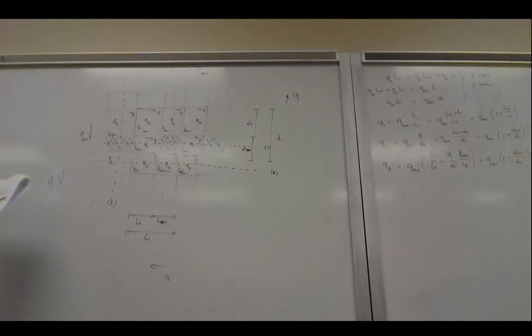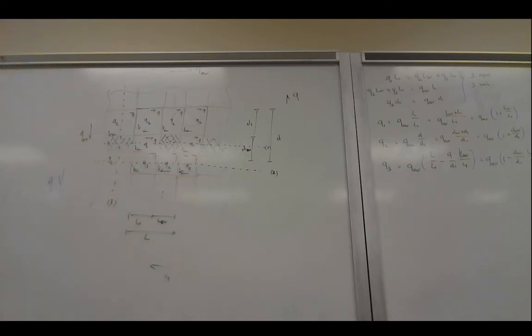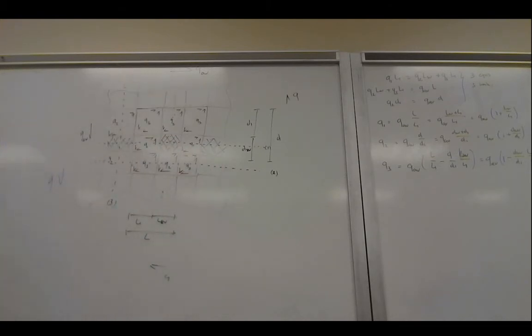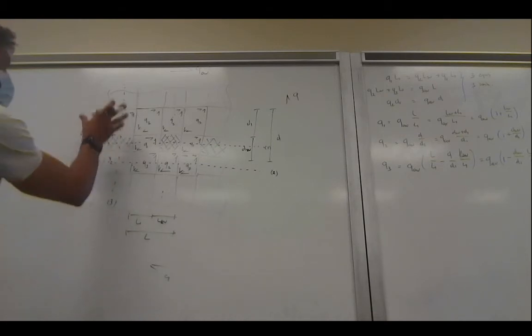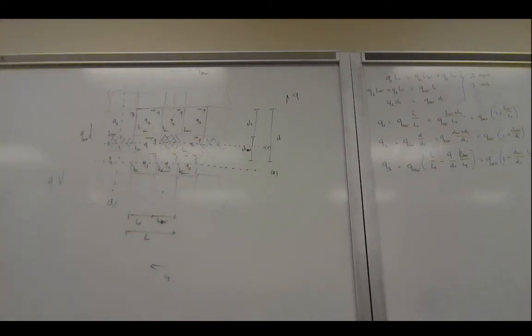So this is basically valid for when we have the periodic cutouts both in the longitudinal direction and in the vertical direction, circumference direction. But again, that's a very special case. What we can do is also assume that we only have periodic cutouts in the vertical section, but not in the longitudinal direction, or in the longitudinal direction, but not in the circumference direction. And what it basically does is it changes one of our equilibrium equations that we started off with.